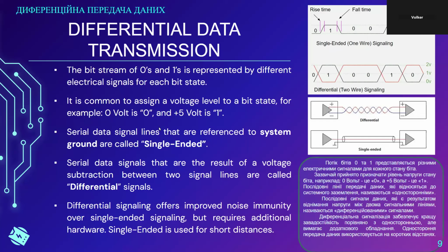So that is the reason why pretty much every modern serial bus, every modern high-speed and off-board serial bus, is using differential signaling. USB is using differential signaling, RS-485 is using differential signaling, Ethernet is using differential signaling. Pretty much every serial interface that goes off-board uses differential signals because of this vastly increased noise immunity, even if the cost is an additional wire.